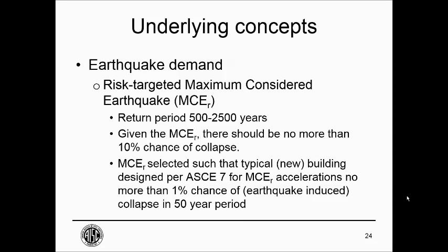There are a lot of approximations in the methods, and I wouldn't say that truly our codes are calibrated to a 1% chance of earthquake-induced collapse in a 50-year period. But on paper, that's how the mathematics, the probabilities are treated in order to get our design base shears for each of the systems.